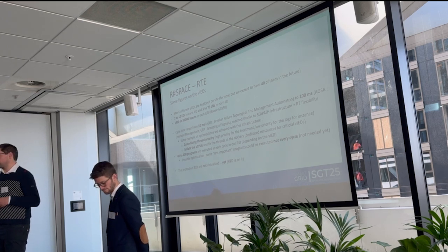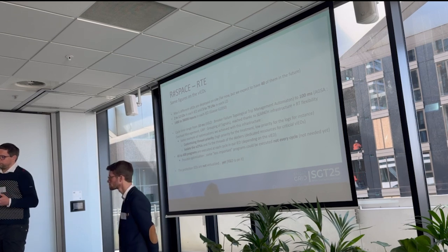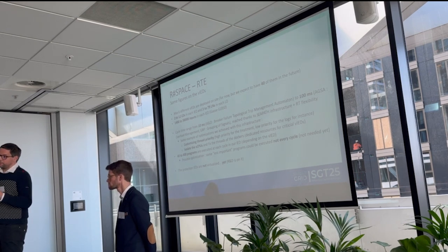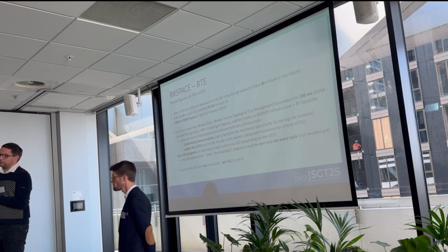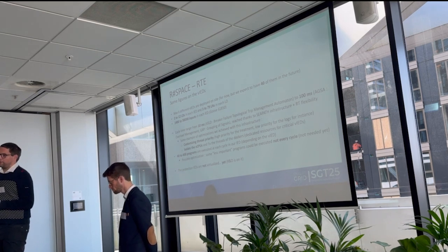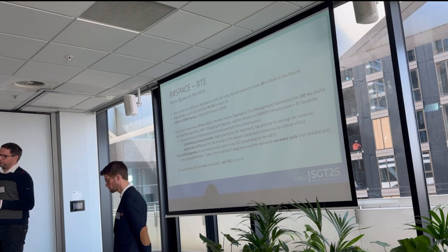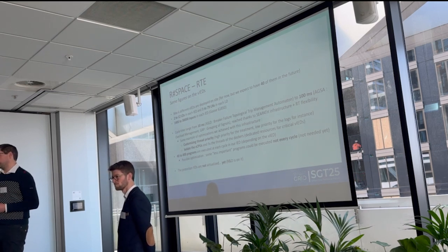Exactly. So we will have some storm of events, some maybe not realistic inputs, but we will test it and we will check each time if the time cycle is respected, so if we are not overwhelming this time cycle. We will check also, of course, our IOs and network, the load of our network. Check also our CPU usage, RAM usage. For instance, as I said, in normal situation, but we are trying to do some more elaborate tests on this.